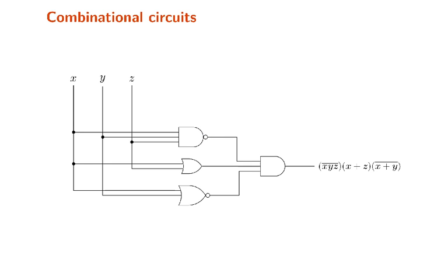So, for instance, in this case, the first X goes here, the Y and the Z, so we see that here enter X, Y, and Z. And so as an output here, we are going to have X intersection Y intersection Z, right? Because this is an AND gate. We can say X and Y and Z. But because of this negation here, we are going to have this output. So this is the output then from the first gate.